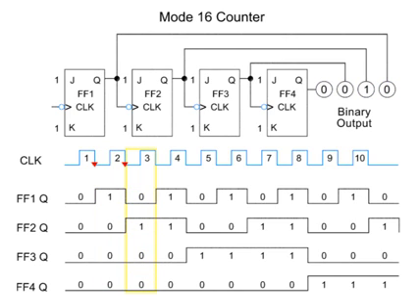As the remaining pulses arrive at the input, the third pulse toggles Q1 back to 1, with Q2, Q3, and Q4 remaining unchanged, and the output is 0011. Pulse 4 again toggles Q1 back to 0, with Q2 toggling to 0 and Q3 to 1, with Q4 unchanged, and the output is 0100.